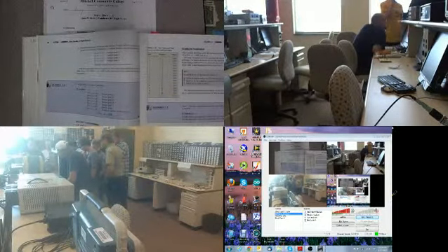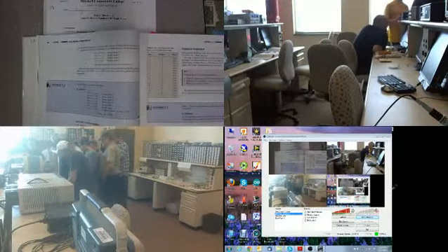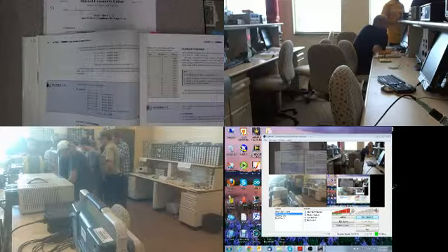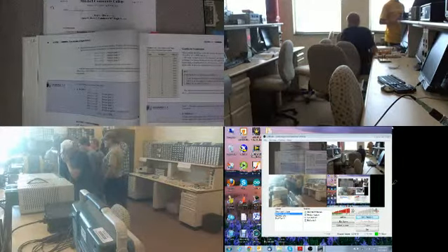This is the OR gate 32 package. In order to have a 3-input OR, we only have 2 inputs on these, so we want 3 inputs. It says 3-input OR out of a 2-input OR. That's the key statement right there. We only have 2 inputs, we want 3. So how do you do it?